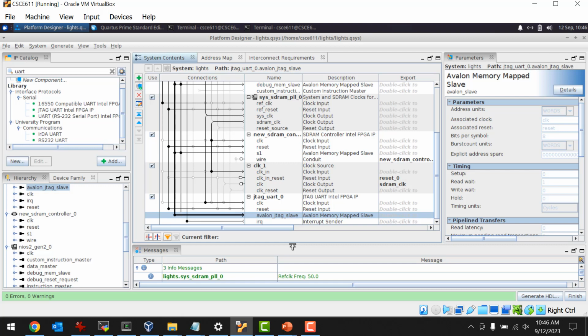It's pretty cool. It's not a great way to debug. It's better to debug in the simulator. But if you have a situation where the simulation worked but the hardware doesn't, that's the only option. Then you have to use Signal Tap. Simulation is supposed to match the hardware, but only in an ideal world.